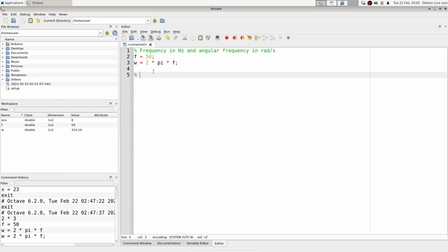I'm going to create my reference phasor. So in this case, my reference phasor is going to be Vs. That's the supply voltage. And I'm just going to set it equal to the RMS magnitude of the supply voltage, which is 230. Okay, what other circuit elements do I have? So we've got R1, which was equal to 1 kilohm. So what I'm going to do here is type this in using the following notation, 1E3. So the E3 here means times 10 to the power of 3.